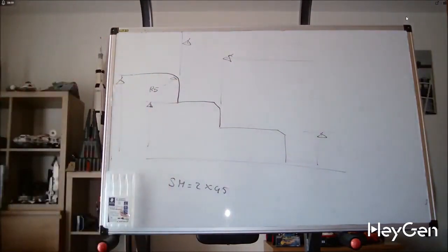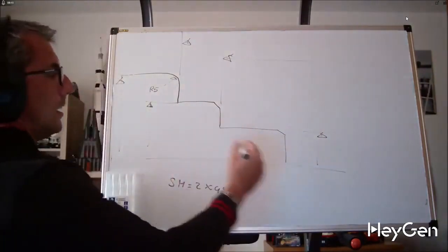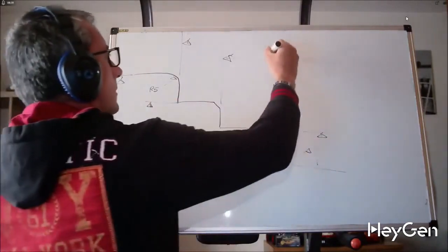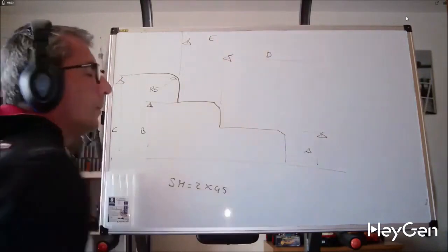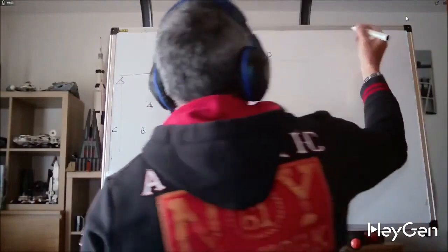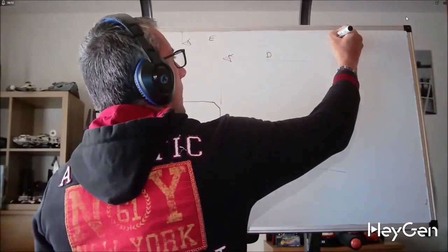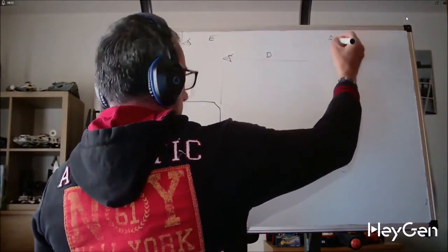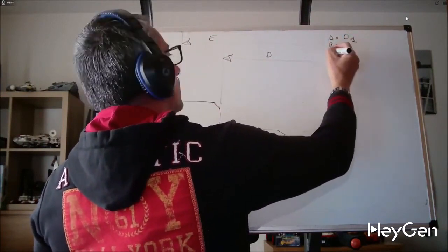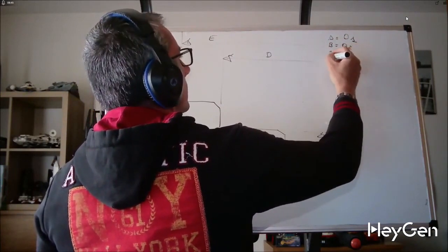I can create a program that very simply, instead of X and Z, so what do I do? At the beginning of the program, I need to identify these variables, which are crucial for the subsequent steps and ensure the program runs smoothly. So A equals D1, which is the first dimension, B equals D2, the second dimension, C equals D3, the third dimension, D equals L1, the first length, and E equals L2, the second length. These variables are foundational to our calculations and operations.